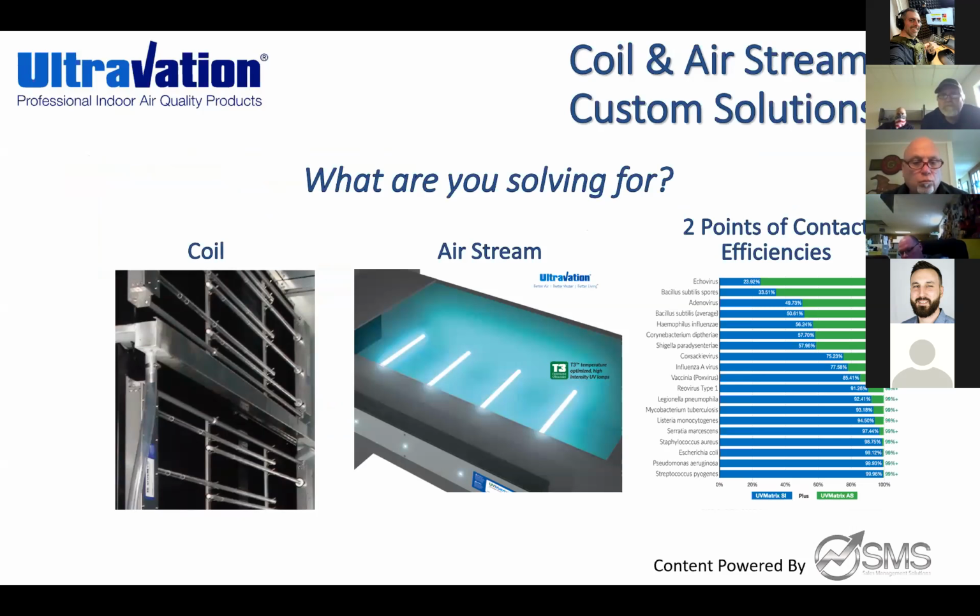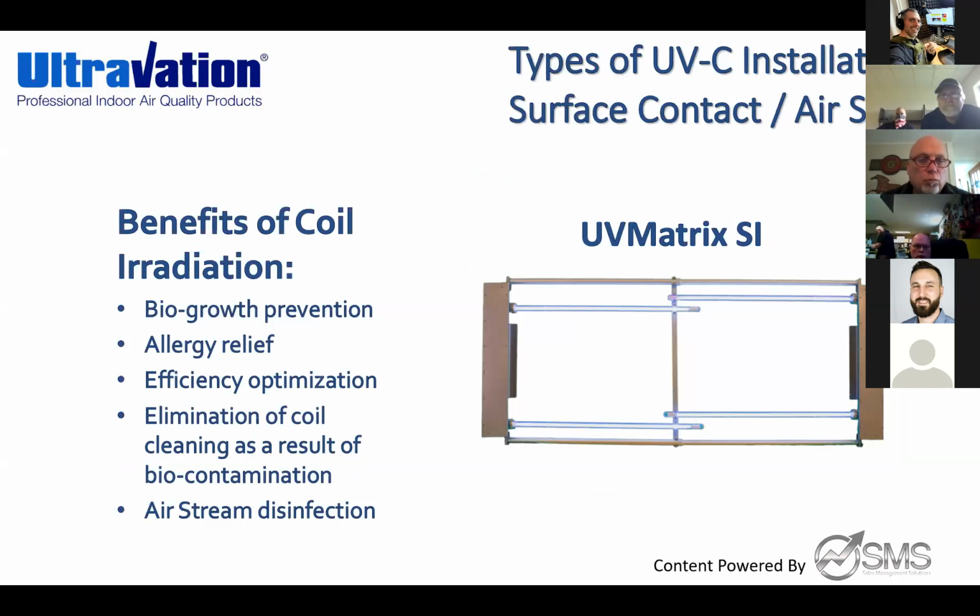So again, before we get started with our recommendations, we always have to ask, what are you solving for? Is it going to just be coil treatment that's going to start fighting bacteria, or is it going to be airstream disinfection that's going to start fighting viruses, or, as we always recommend, that you do both. And once again, we do have that chart there that shows what surface treatment will do, but also what an airstream will do and how they're much more efficient if you do both. So go ahead and jump to the next.